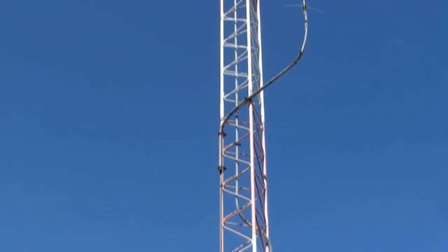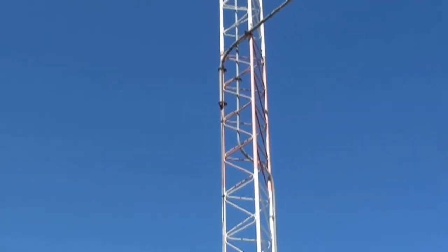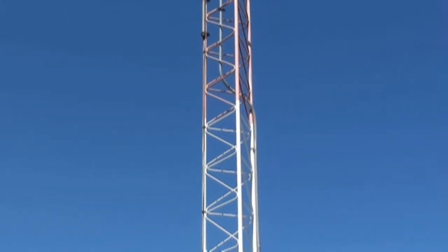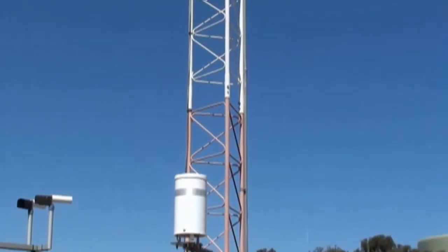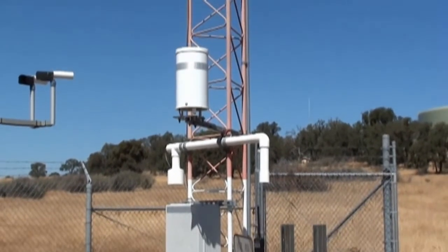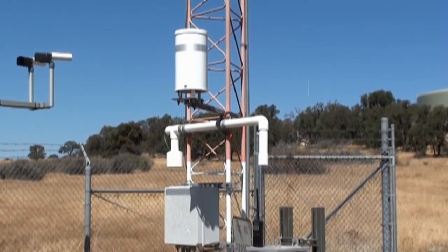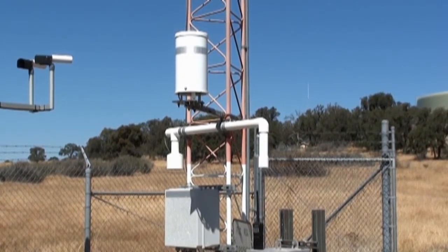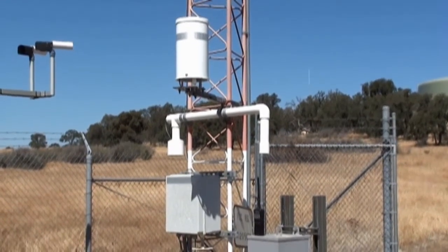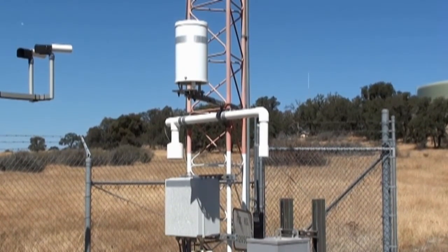Lower on the tower, we see several devices used to both gather data and augment it. The cylindrical C-shaped object that's about 1.5 feet tall and about 8 inches in diameter collects rain and augments the information gathered by the visibility sensors. Below that is a U-shaped 2-inch diameter pipe which houses the probes for detecting dew point and temperature. The pipe enables accurate readings by shading and ventilating the probes.